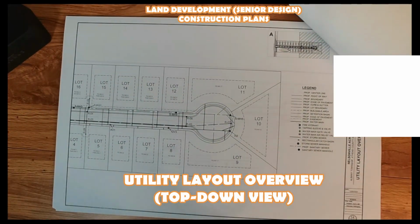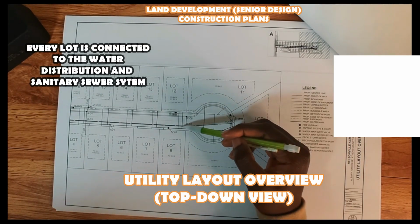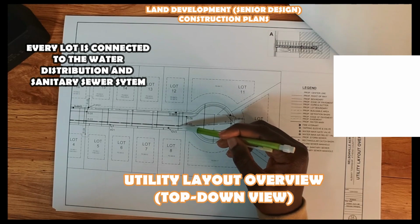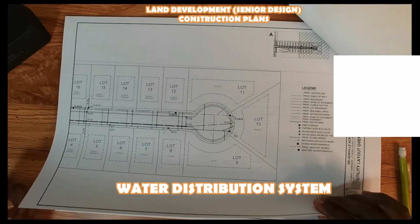All right, so this is just a closer view of the utility layout. Let's pick out lot 8, for example. As you can see, it has a connection to the water, and then there is a connection to the sanitary sewer. Where is that? Yeah, this is it right here. So this is sanitary: all the waste water coming out from this house will go here, and then the water goes in here. We have that for each and every single home.